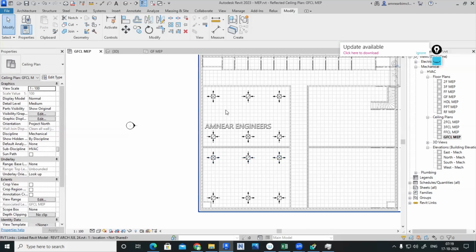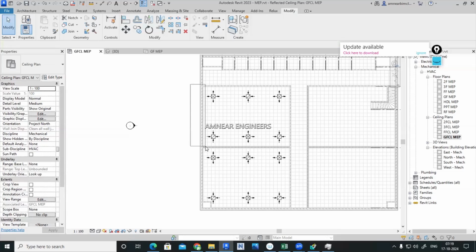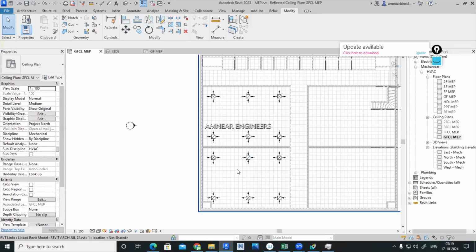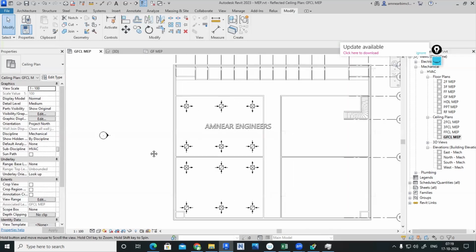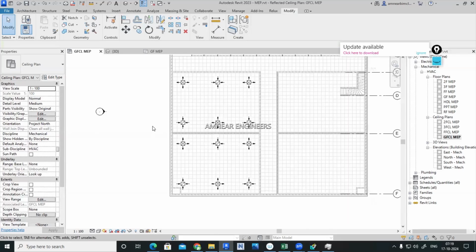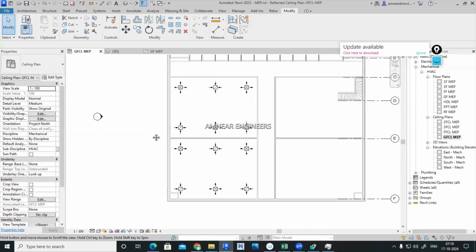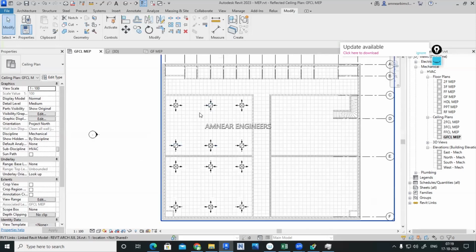Because this room, we are having only one side exposure. Only this side is exposing. But for this room, we are having two side atmospheric exposure. So the coil load will be slightly more in this room. Ground floor office 2. Okay. Anyhow, for time being, just let me do that. It is not a design class. Design class in depth, we have already studied in the project session and all. So we can continue. So I'll be placing my fan coil unit there.